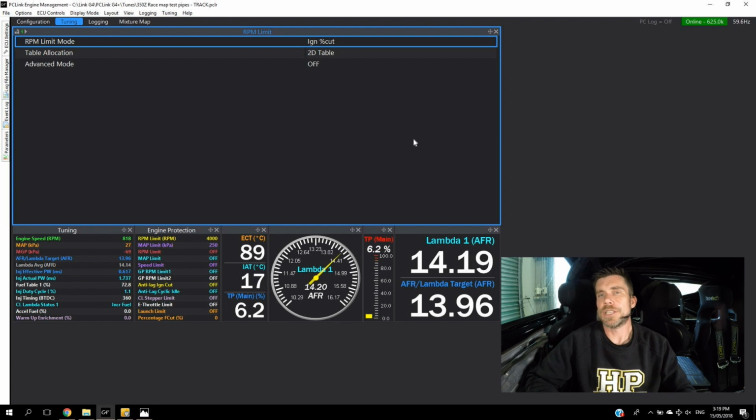So it is possible to end up with one engine cycle where we may end up with some combustion. It is likely to form a very lean mixture if it does combust at all, and it's also just a brief one cycle. We're not going to end up with a continuous lean condition, but just to explain what will happen with that fuel cut. Also, when we then reinstate the injection, we also need to initially build up that fuel film.